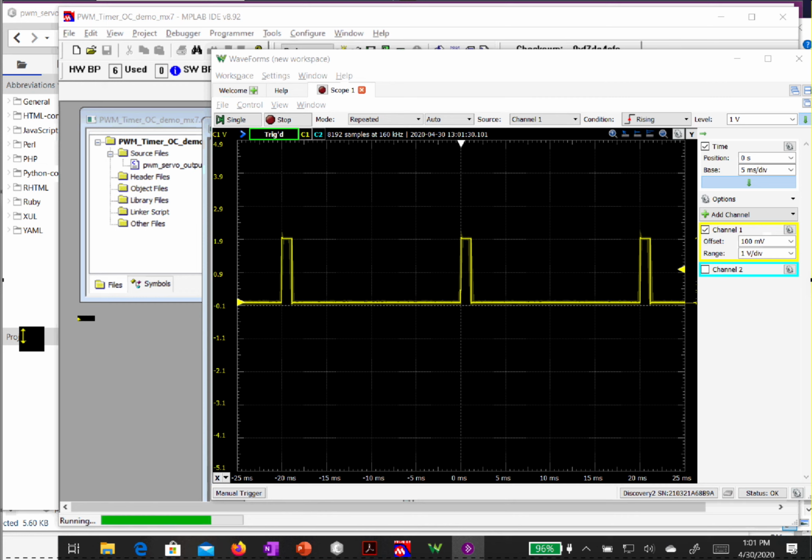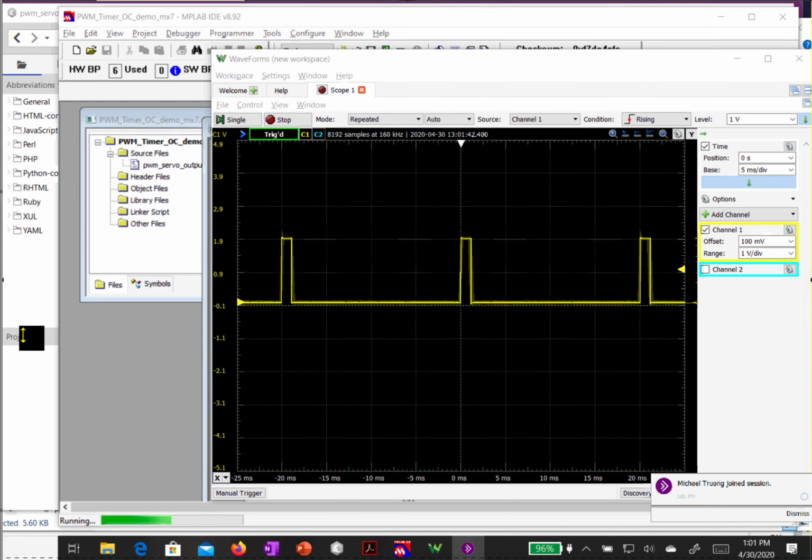So what we're going to do next time is we'll actually use some of these motors, and then we'll talk about a different class of motor called the stepper motor. Stepper motor is different from a servo motor in that the stepper motor uses a different sort of excitation of the windings. So on this servo motor, you have a constant bias on the windings, and then you provide a control signal. On the stepper motors, now we're energizing windings in a certain sequence to allow them to be able to move either with coarse or fine positioning.